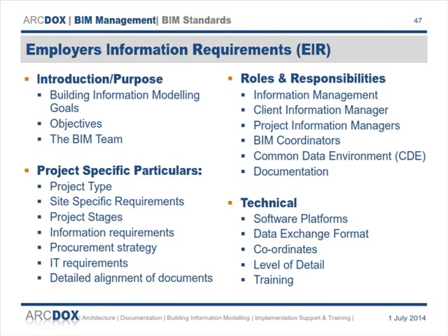And then obviously there is software involved. There are processes for exchanging information, how that works, whether you're all using the same software package. If everybody's using Revit, that's great. If they're not, how are you exchanging information between the different packages? And what level of detail or level of model definition are you working to at the different stages of the project?